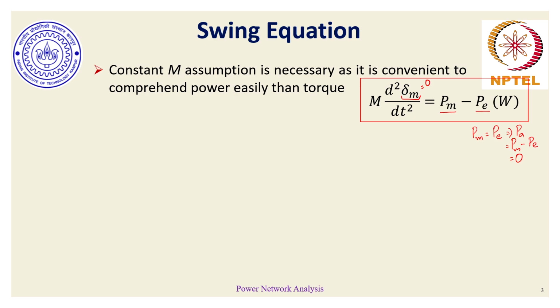There are several assumptions involved in transient rotor angle stability analysis. One of the assumptions is that network dynamics or network damping is neglected. The change in input mechanical power or input torque is assumed not to exist, because the associated turbine and governor dynamics are very small compared to the transient period of study in which we want to analyze the stability problem.